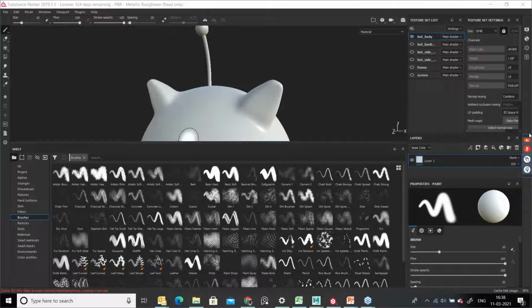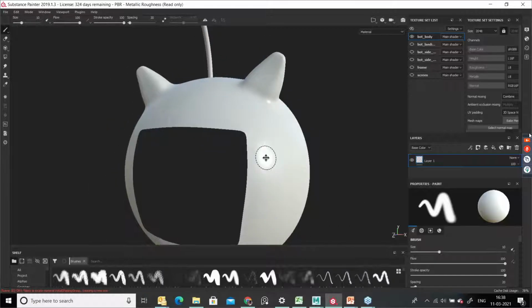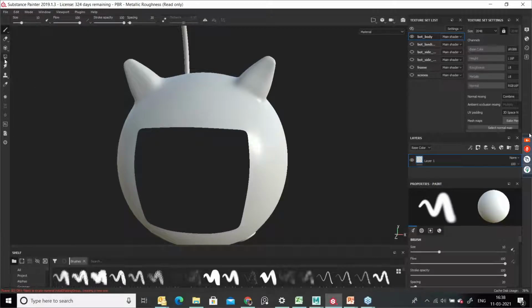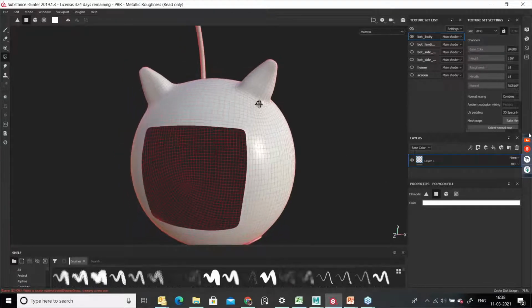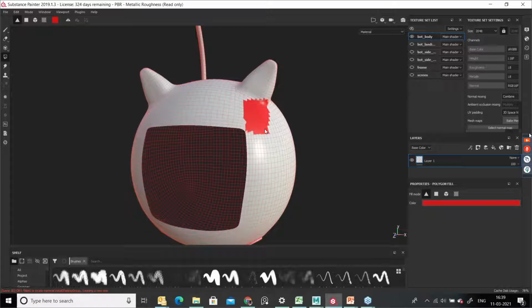Okay, so here just now we crossed this one, how to isolate the geometry, we discussed. Now polygon fill we can finish, then we will move one by one. In polygon fill you can select the geometry and apply a specific color on the geometry based on the quads or based on the triangle. Now I am trying to check the triangle option over here. Before that, I am trying to change the color over here. Red color. Choose the triangle option and just drag. What happened? See here.